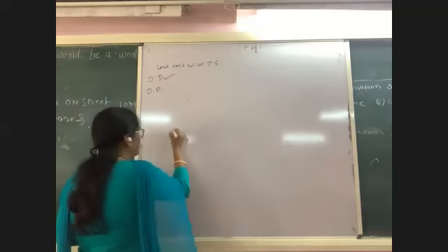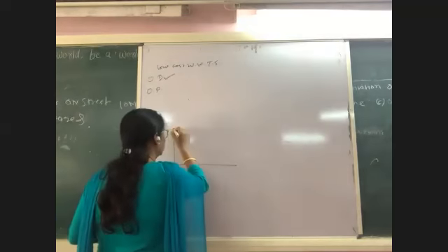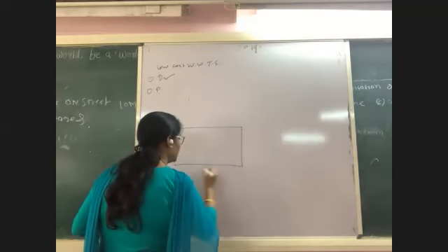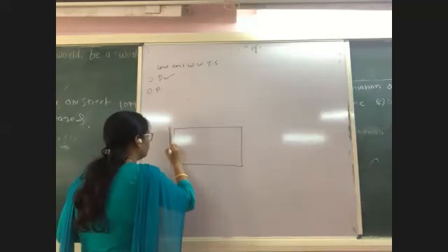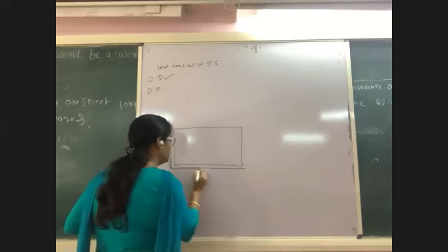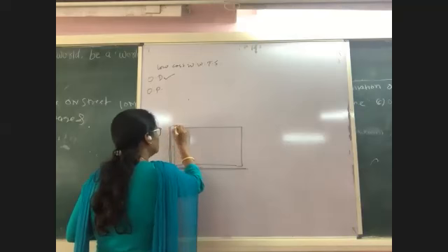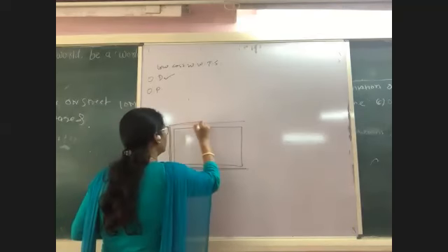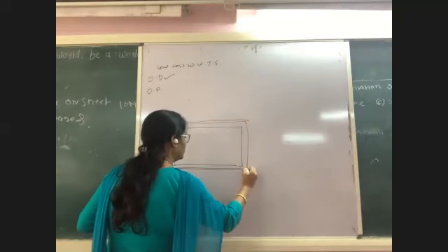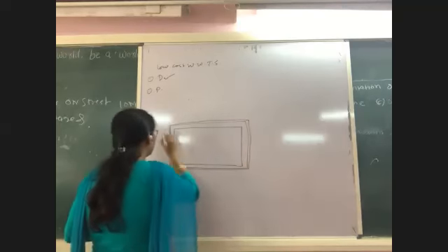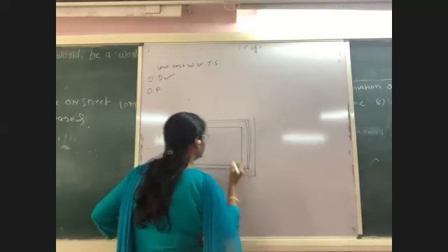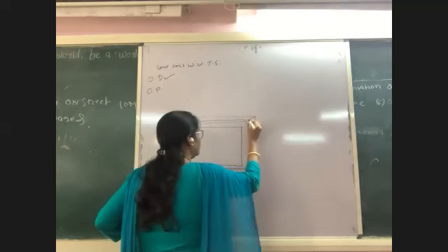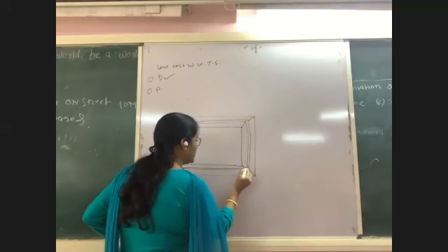Okay, the oxidation pond, I have shown you the figure, you have drawn it already. It can usually be designed rectangular in shape. A wall can be constructed which should have a slope on both sides, towards the inside as well as towards the outside, to get proper strength for this wall. Then the sewage will be allowed to enter at the center of this tank.